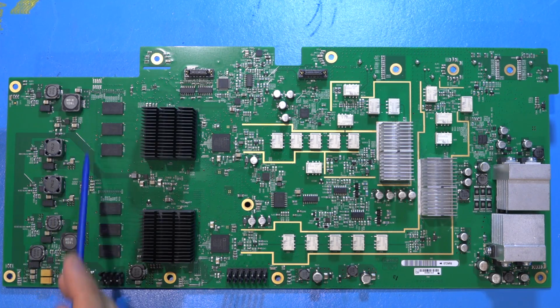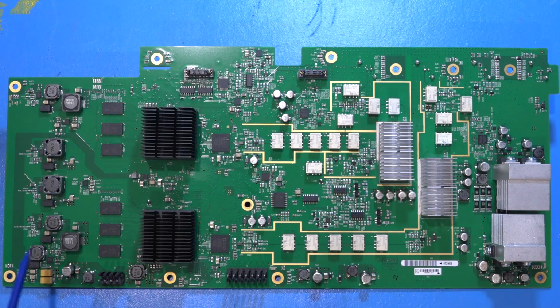The next components are going to be memory and some digital circuitry. Now, this digital circuitry is obviously going to also be potentially putting some noise on the analog devices, but at the same time, these are all using differential LVDS signaling. So their EM footprint on the board is actually not that bad because everything is differential. So this memory is going to hold all of the arbitrary waveform and the data that you want to transmit directly on the RF channels.